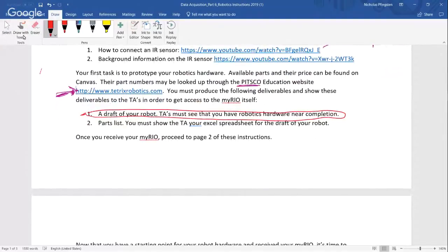We have servos called continuous rotation servos that spin like a DC motor, and we also have standard servos. If you work with servos, you know a standard servo just moves to a particular position. So you have a standard servo that controls the steering and a continuous rotation servo on the back that drives. We've also seen that approach. I'll say a little more about standard servo versus continuous rotation today as well.